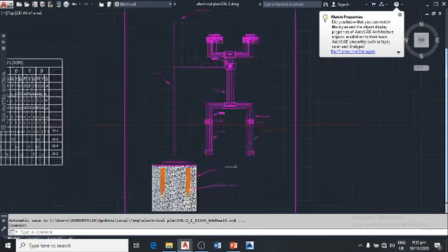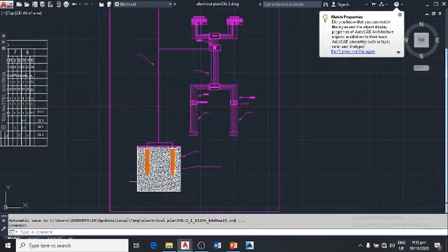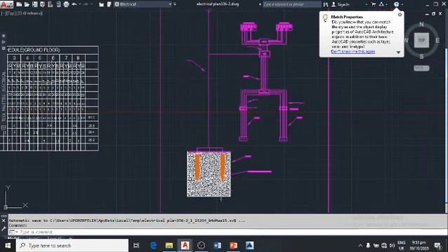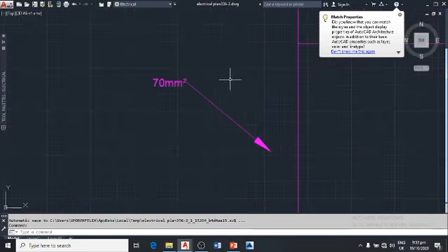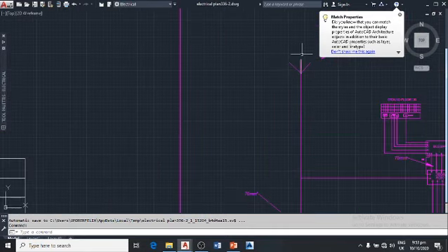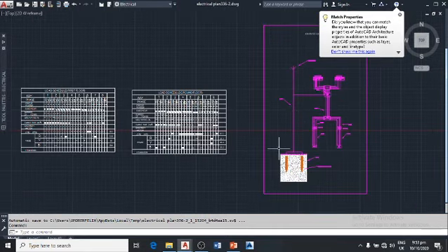Okay, for the labeling, this is the ground, that's the earth, this is the copper rod. Go to a shop and ask for the copper rod for earthing, then you can see how it takes its shape. Okay, we have a wire coming in, we're using a 70 square wire for the connection of the thunder arrestor down to the earthing.